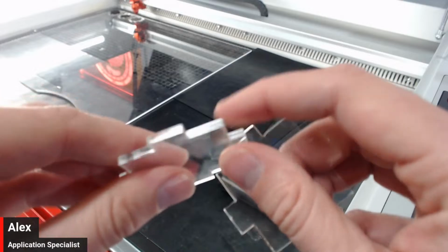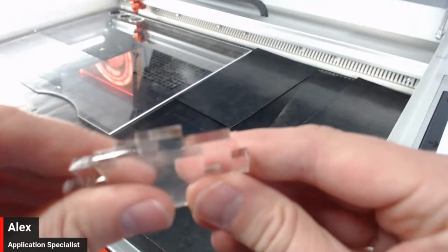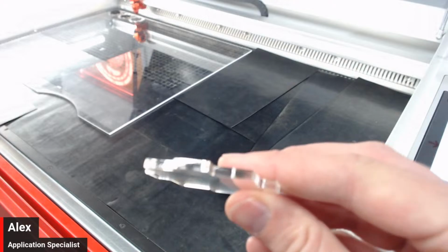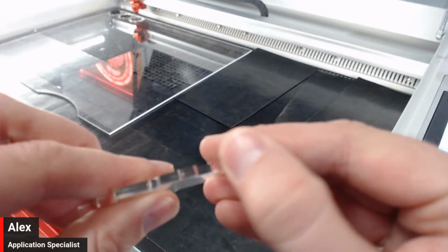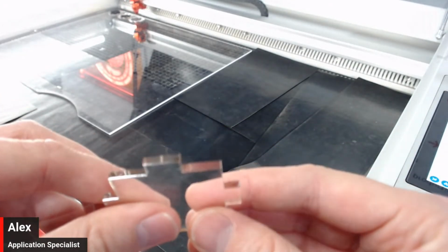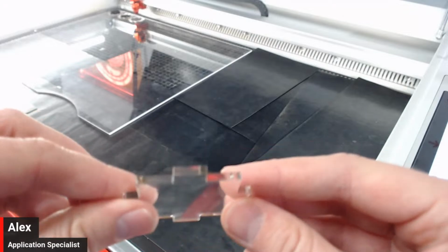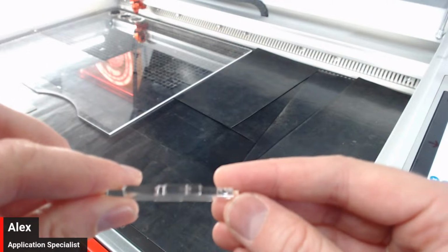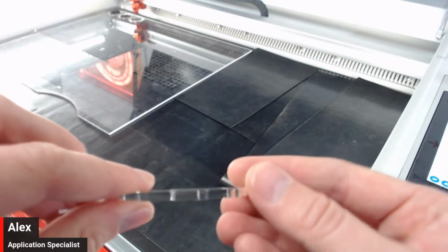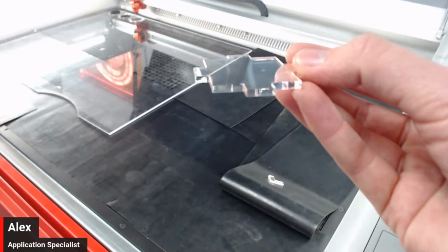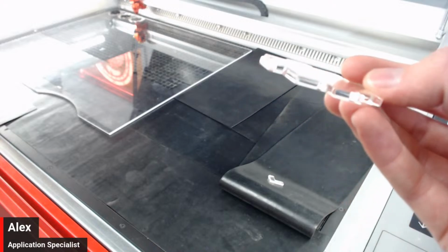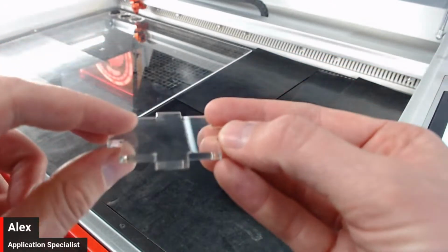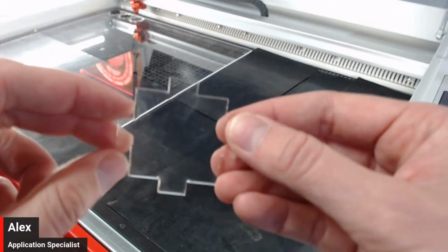But it also depends on your hardware as well. So in order to achieve your super glossy edge on your material, there are two things required. You need that right heat into the material, so your laser power and speed setting. You then just need to be very wary of the actual setup to make sure it's safe for the material, so reduce that risk of flaming. So that'd be things like lifting the material up off the bed, usually something like a disposable or a sacrificial acrylic slat table, something like that would all aid those.